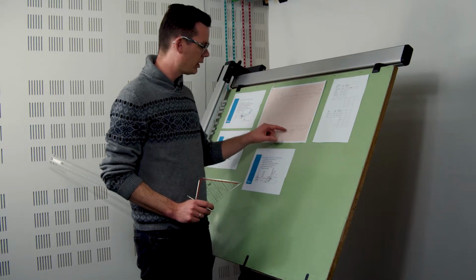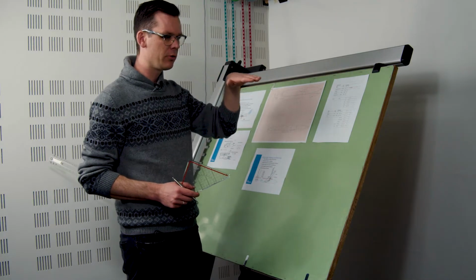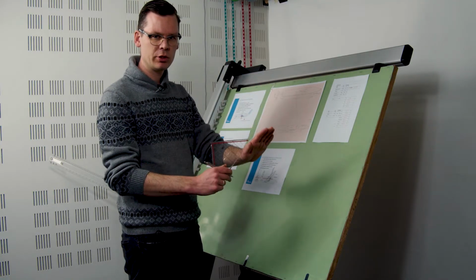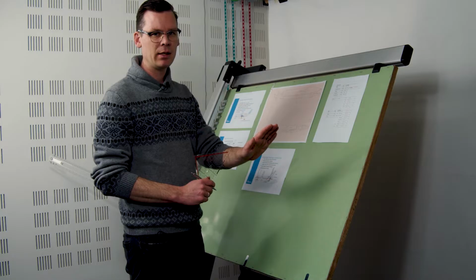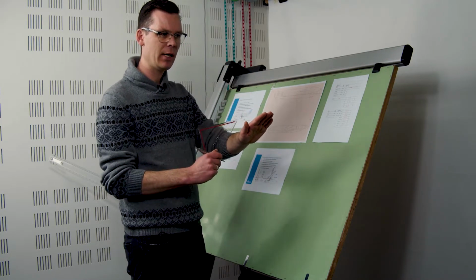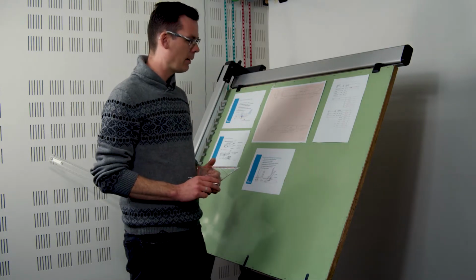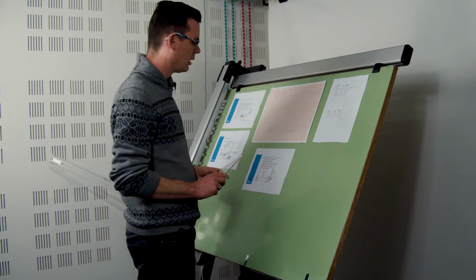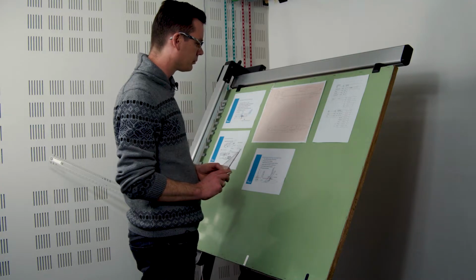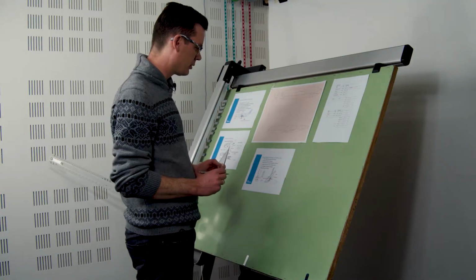We know that when the CG is shifted fully aft, and this airplane is, for example, making a landing, we do not want the center of gravity to be behind the main landing gear wheel axle. Because if the CG were behind that axle, the airplane, due to inertia, would over-rotate and tip on its nose. Now, I'm deciding here that I choose an angle, my longitudinal tip over angle, and I'm choosing 12 degrees.